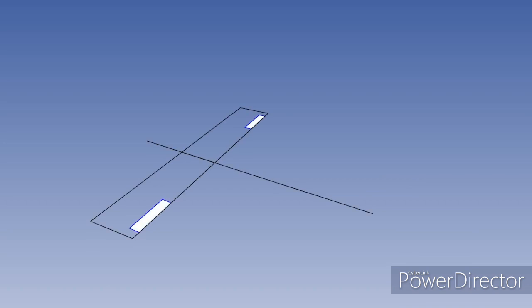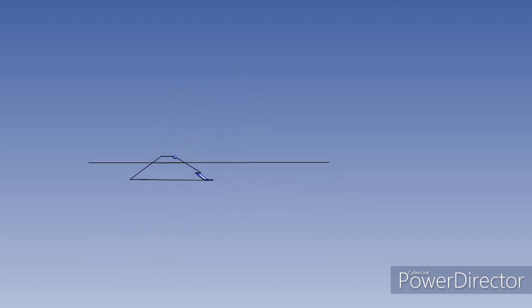The second byproduct of rolling the aircraft about the longitudinal axis is adverse aileron yaw. The objective when rolling the aeroplane is usually to turn to a different heading, as previously described and here animated. If both ailerons move through the same angle from neutral, the downgoing aileron will generate more drag than the upgoing aileron. Parasite drag is the same on both, but the downgoing aileron would generate an increase in induced drag, and the upgoing aileron would generate a decrease in induced drag.